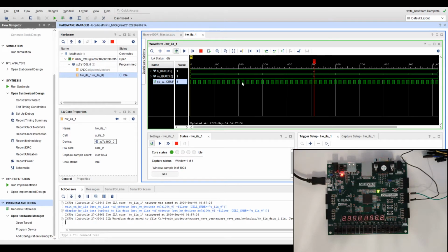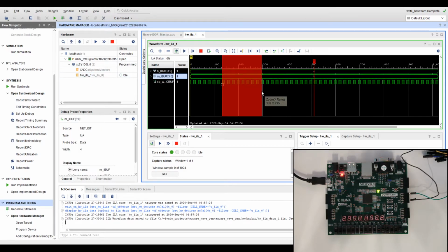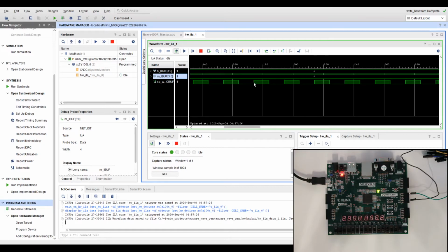So you can see the waveform generator is actually generating a 1 and 0, and M has 1 and N has 1. And you can definitely zoom in and just see it even more, and you can look at it exactly like what we did in the simulator. So if we jump from here to here, we're going to see 174 all the way to 184, and the difference is 10, and you probably would be thinking, well, shouldn't it be 100 nanosecond?